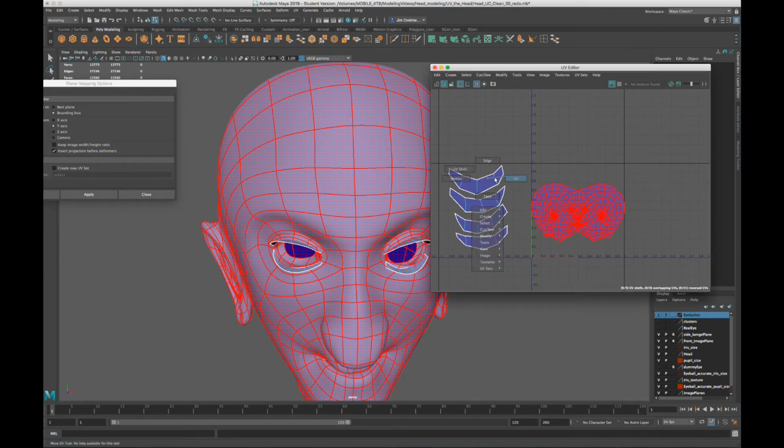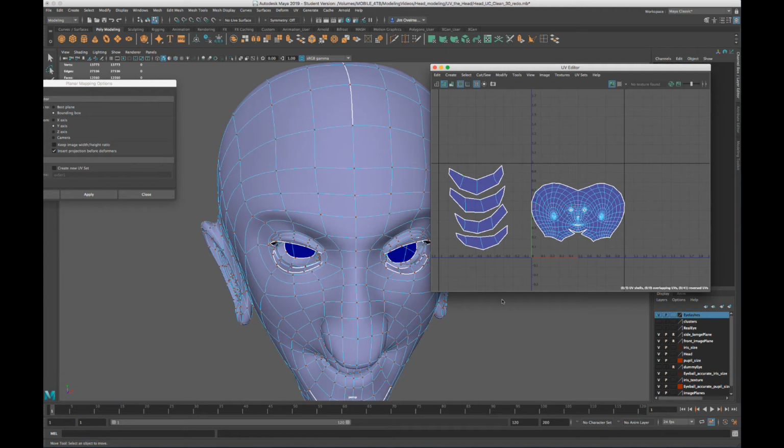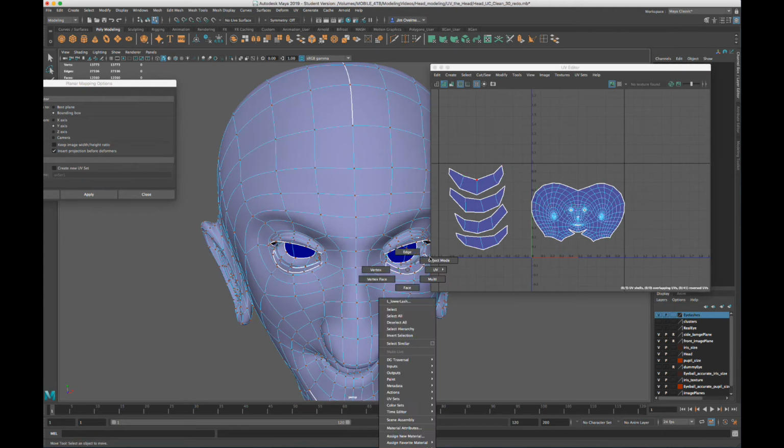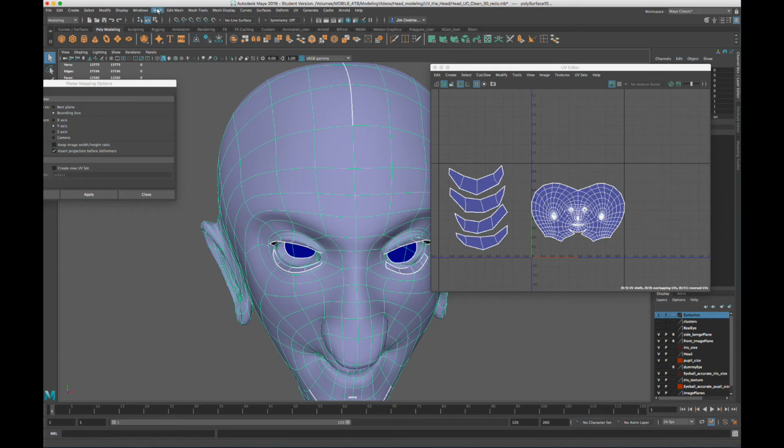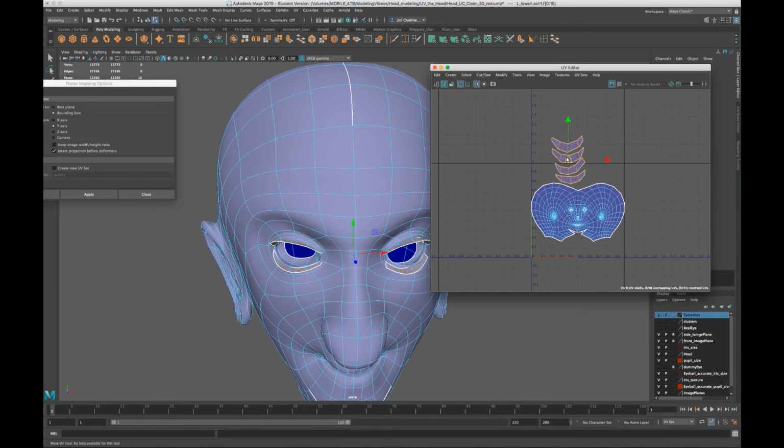And there's a couple reasons to do different things here. If we want them together in one, simply what we could do is select with shift all four and the head mesh and say mesh combine. That puts them all as one, and now you can UV them as one as well and bring in the UV shell and place them, resize them perhaps and find a space for them. And remember, we're going to combine all those together eventually. There would be a reason not to keep them together, although this would be the most efficient.